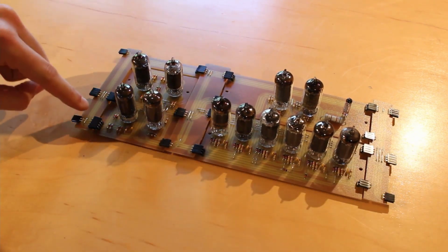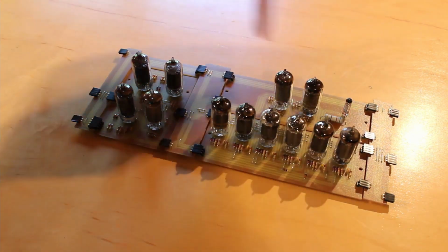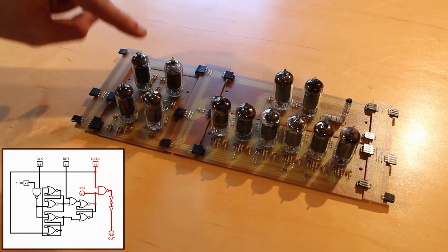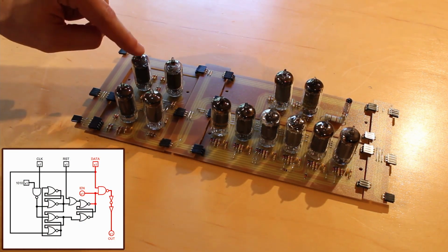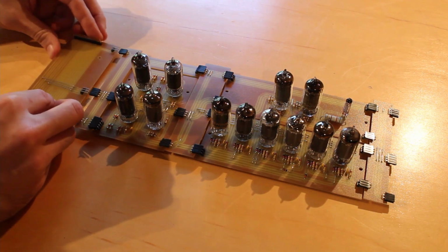And this top board here also carries the input enable register signal all the way back over to here, because that input enable register signal is also being input into this other NAND gate here. Now the final input that we're missing is the data from our data bus. And that's actually going to come from our end piece, which has a bunch of connections on it.